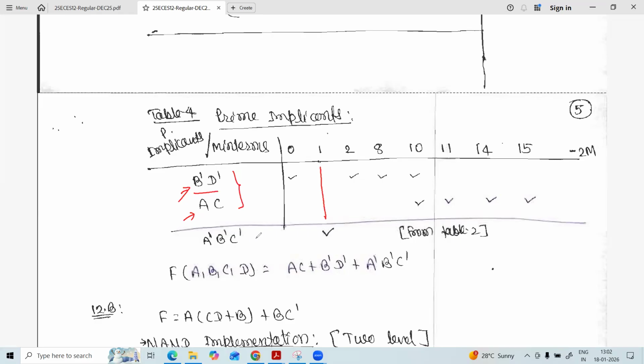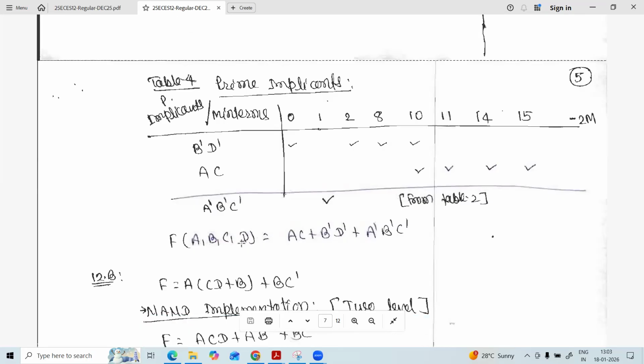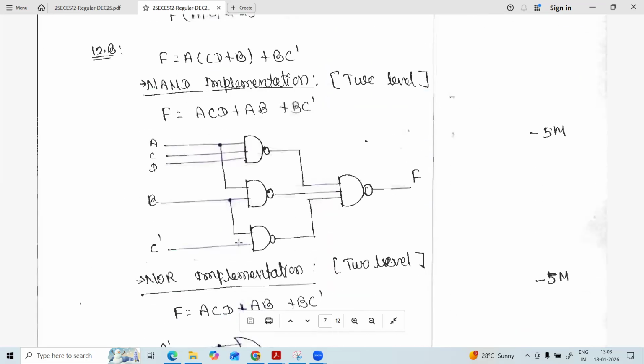So now we'll go back to the previous table where minterm 1 was available. For that we have the combination with literals A', B', C'. By this, minterm 1 is also covered. So finally this is the final answer in terms of sum of products. This question is attempted by the maximum people, but still 80% of people didn't reach the last stage.